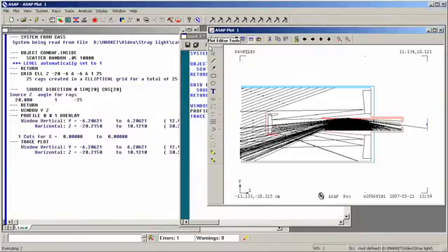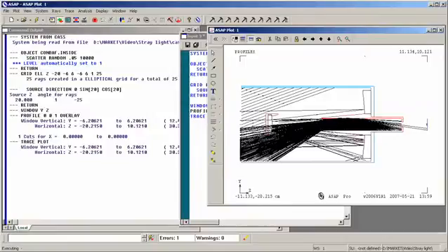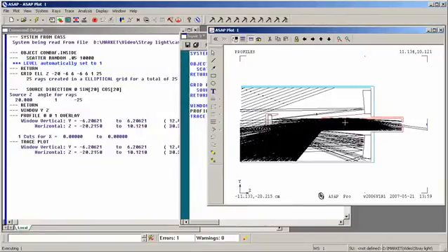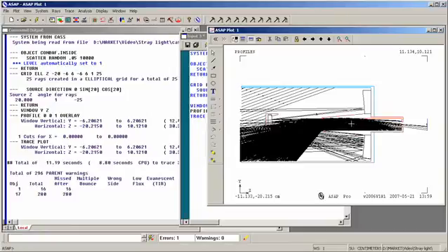Here's our ray trace. We can see some of the rays have hit the conical baffle, and we can see many scattered rays coming off of this conical baffle, scattering into the hemisphere over that interior surface. Now we see our first problem. Even though we've asked for very many scattered rays, 10,000 scattered rays for every incident ray, none of those rays actually got to the detector. We're going to end up with no power whatsoever on our detector, in essence saying our stray light is 0, which is the wrong answer.